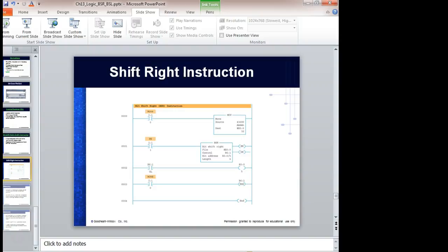So they didn't put a group here that told you the bits. You can look at the data and the instructions in those manuals, and they will tell you all the registers that are controlled. But the status register for this one, the control register, is not in the S file. You assign it one of those control register files, and you do that inside the bit shift instruction itself.